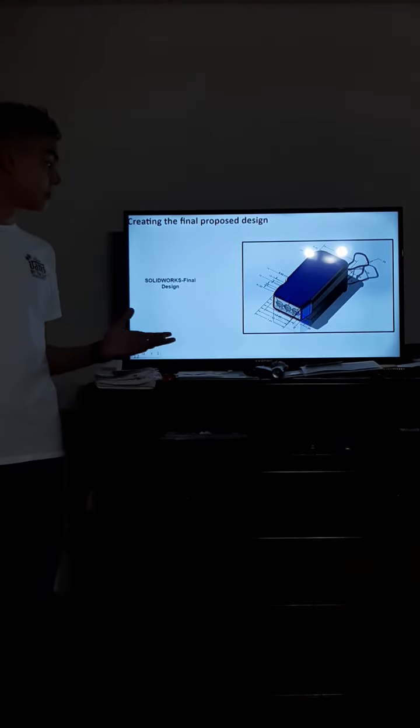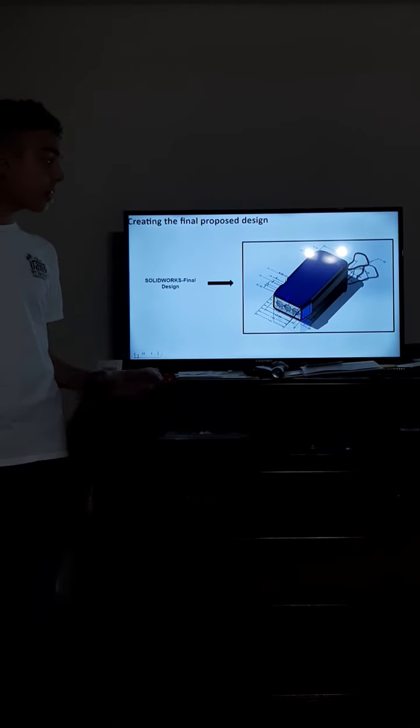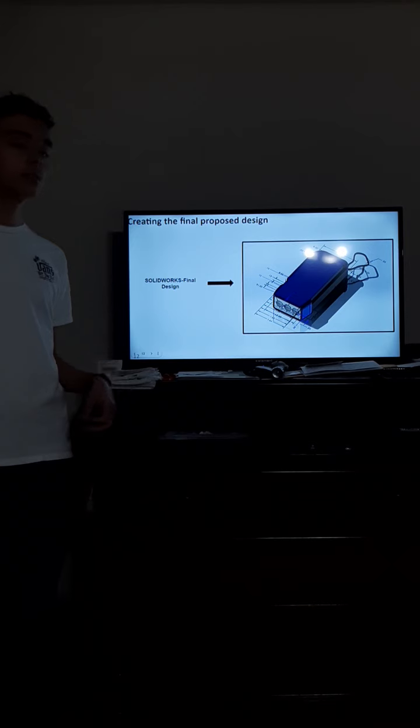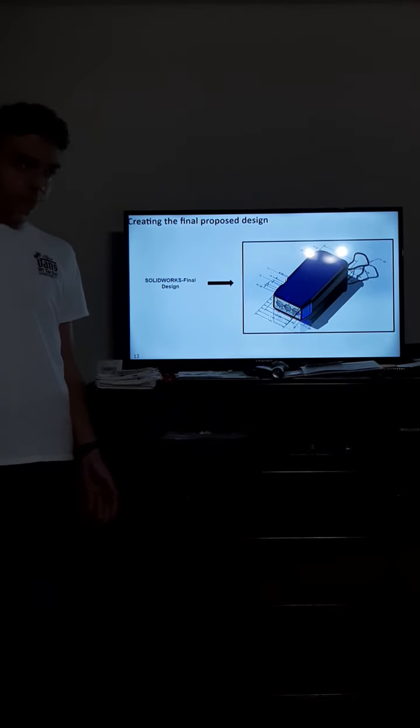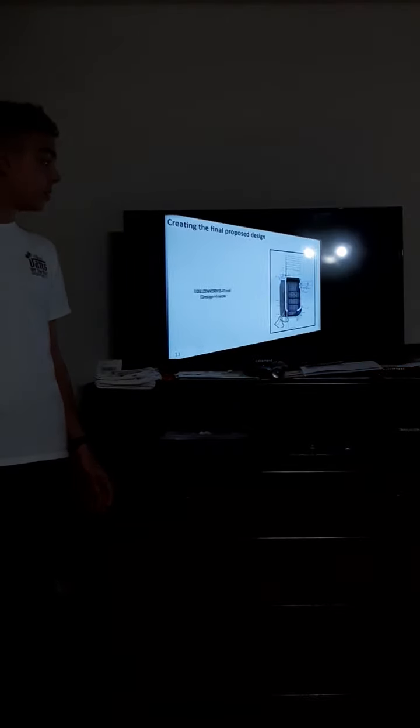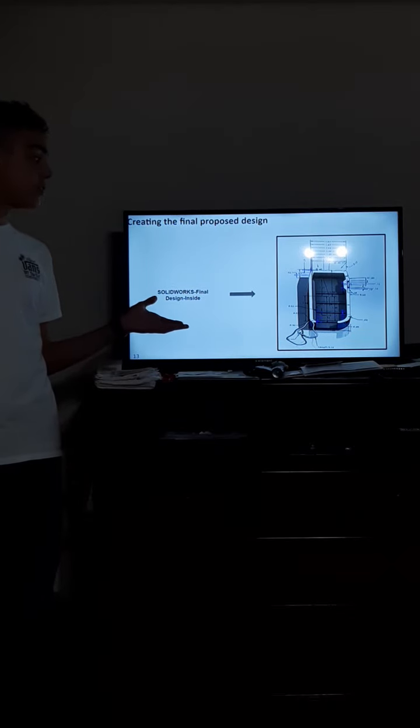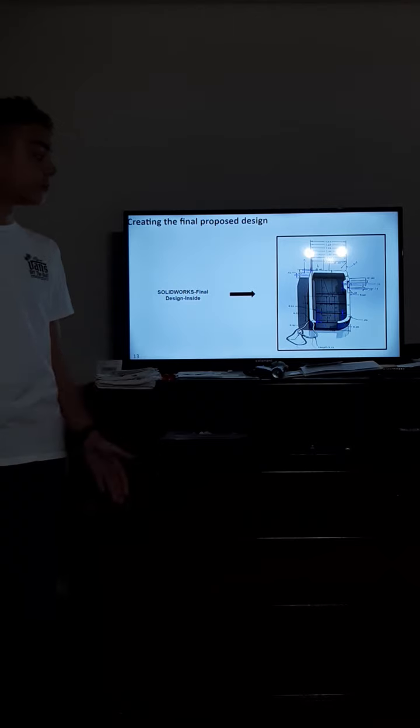This is the first image with dimensions of our final design. It has the higher quality, thicker plastics. We used a significantly higher quality ABS plastic. We also made the plastic solid and opaque. Here, in an inside view of the flashlight, you can see that the plastic is twice as thick as the original flashlight, and that we also added structural ribs to reinforce the flashlight.